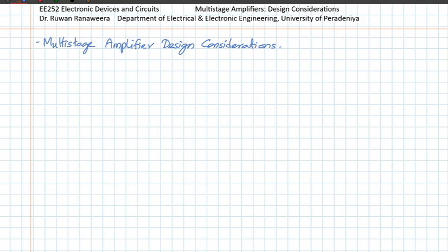Gain cannot be really high. For example, if you want to increase the gain to 100,000 or 1 million, that is not possible without adversely affecting the performance, because inherently, even when there is nothing else, whenever there is a resistor, there is what is called thermal resistance noise.